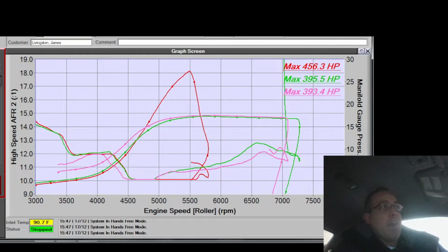They use what's called TMAF, which is even more responsive and helps take out that instrument lag, sensor lag. It doesn't mean wall wetting doesn't exist. It's just because the TMAF jumps so quick, it has this transient period where it spikes and then settles to where it's supposed to be. That transient period dumps a bunch of fuel in the engine, and so the sensor lag doesn't really matter on it. So the other part of tip-in is making up the difference for the sensor lag and all of that.